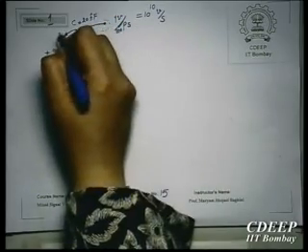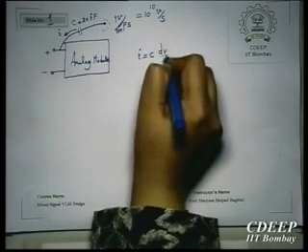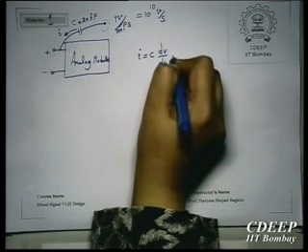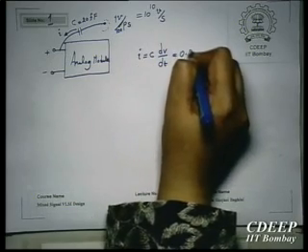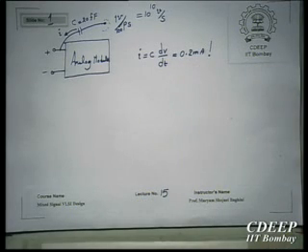Now I calculate this I. So it will be C dV upon dt, which will be 0.2 milliampere. So simply you inject 0.2 milliampere to the circuit. But if you are injecting 0.2 milliampere to an impedance which is high, then practically it is impossible to consider this positive input unchanged. Therefore, it will sense a lot of noise.